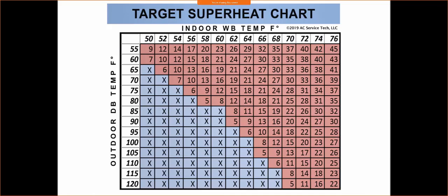Why is this important? Well, it's important because if our system was initially started up, all right, and let's just say the home, the air conditioning system was broke down, hasn't operated for a couple of days, it's nice and toasty inside there, we're going to have a lot of heat inside the building, all right? We're going to have a lot of heat that's not only sensible, but it's also going to be latent, all right?